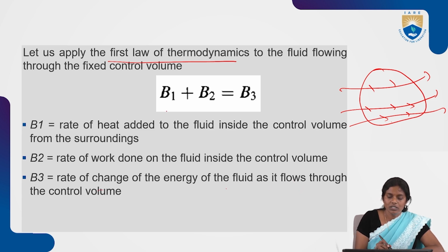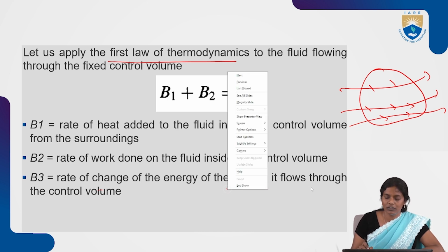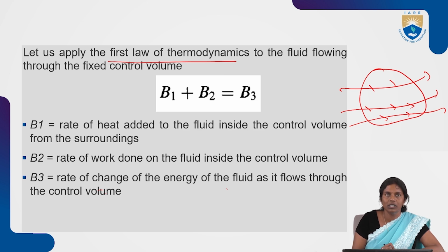So once again, this is nothing but the total energy. The rate of change of the energy of the fluid as it flows through the control volume is equal to the rate of heat added to the fluid inside the control volume from the surroundings, plus the rate of work done on the fluid inside the control volume. That is the first law of thermodynamics.